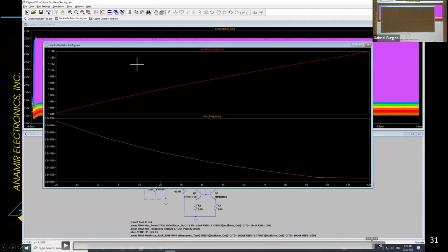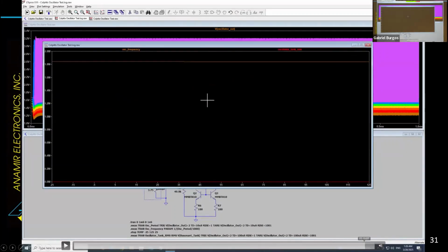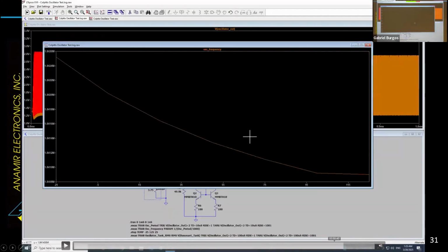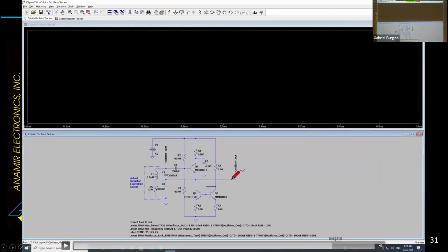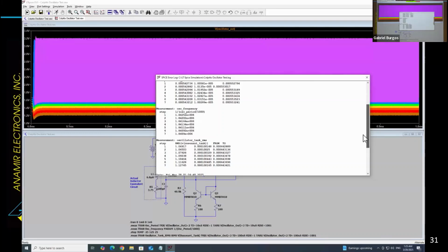I was hoping to find where I've actually measured the change. Did you have to add parasitics to the interrupter to get it to self-oscillate to meet the housing criteria? No, I didn't. Because I've tried to use LTSpice sometimes to model self-resonant transformers, and you end up with convergence issues. Yes, that's true. I've had that problem myself. How do you avoid those convergence issues? Add the required parasitics to get it to naturally oscillate.